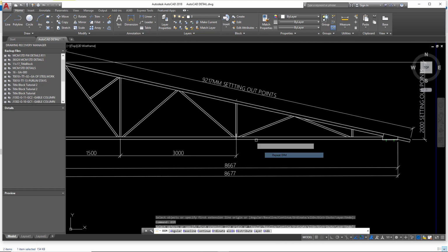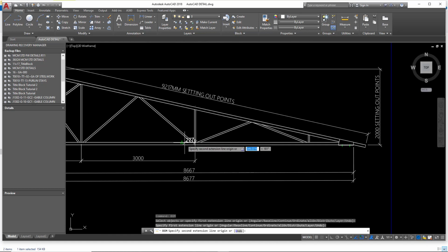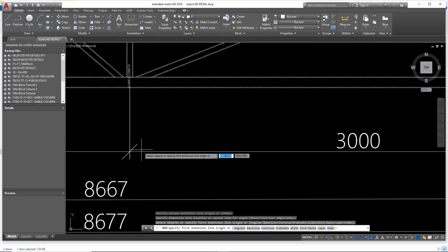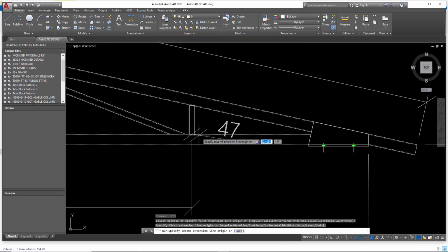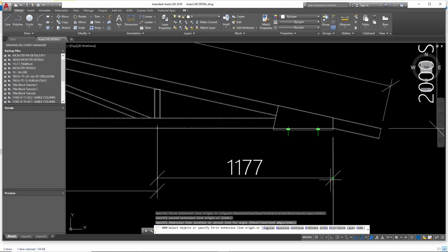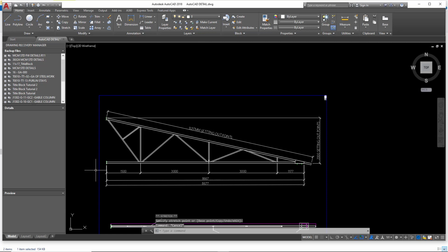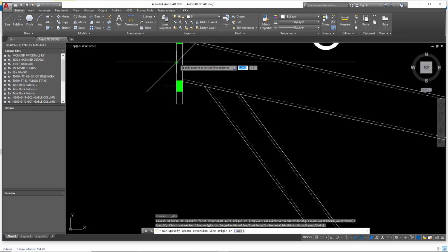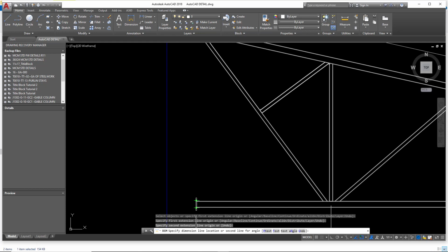Right click, and I'll do the same thing here, and I'll snap, just mouse over here and you get a midpoint, and just mouse over here, you get a midpoint here, and you pull it and place it right there. Then escape and repeat that, then snap on the midpoint there, and we'll snap right here. Just pull it down and drag that, take it down here, and that's how it looks. Now your drawing is growing and we're adding more details here, so let's snap at the midpoint there and snap at the midpoint here and drag it aside and place it there.